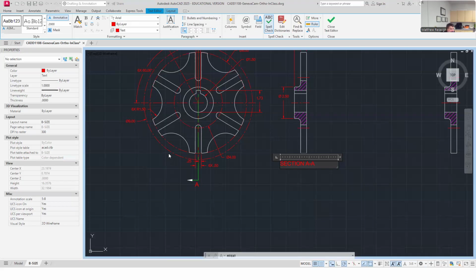Sometimes those get underlined, and so sometimes we'll add an underline. I usually will do a center justification of whatever my text is, but if I have more data underneath here, like sometimes you'll have a different section scale, and sometimes you'll have quantities or materials, I'll underline that, and then I'll have the things underneath it. Scale is the one I think of. If you're going to have a scale different from the scale on the sheet, then you need to say that in the view.